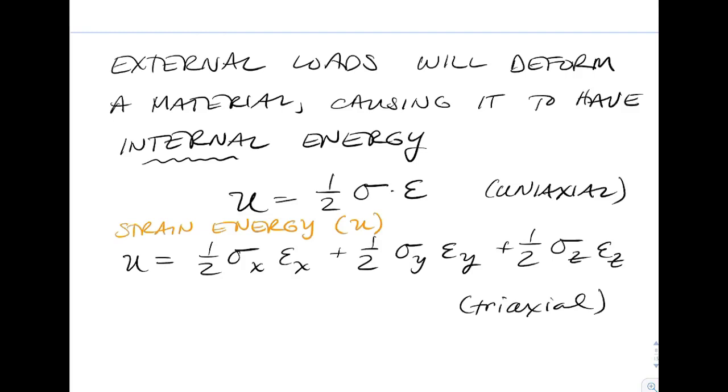So the strain energy involves integrating stresses through strains. So we end up in a linear condition. We end up with 1/2 sigma times epsilon. We can substitute in for epsilon, sigma over E. So 1 over 2E sigma, and we'll go ahead and put yield in there.